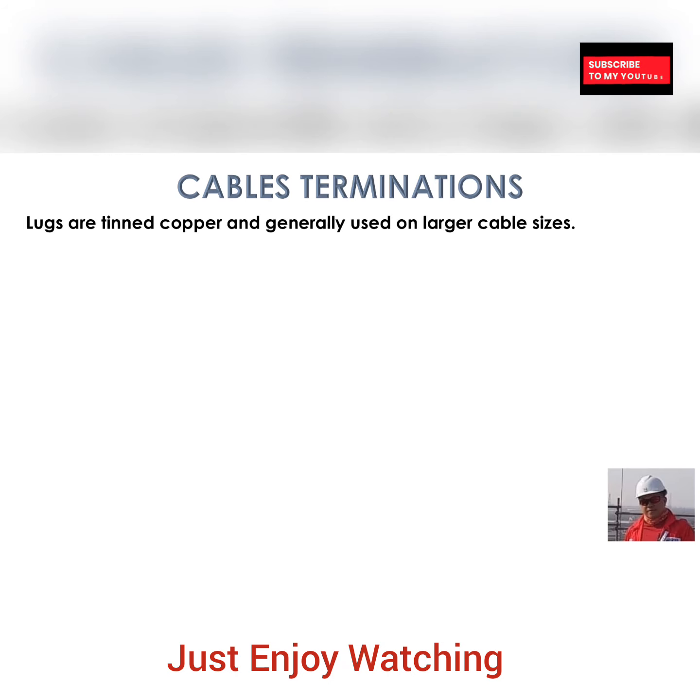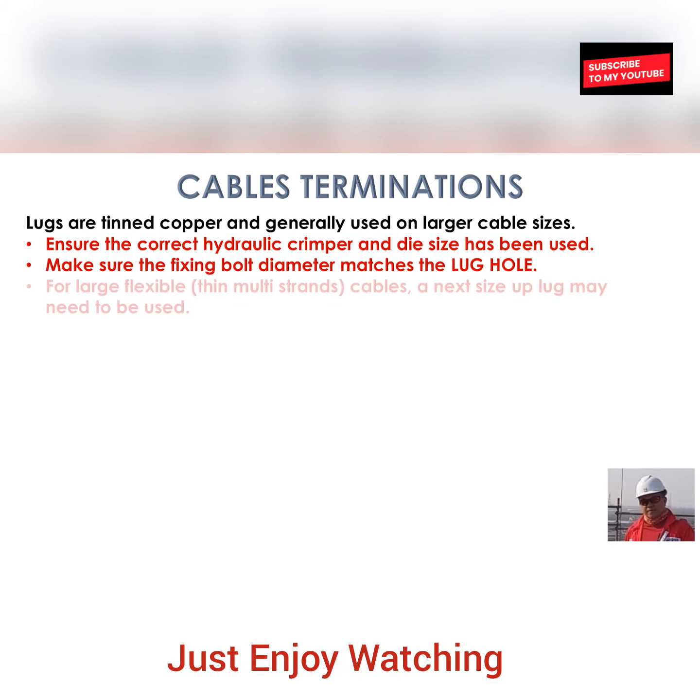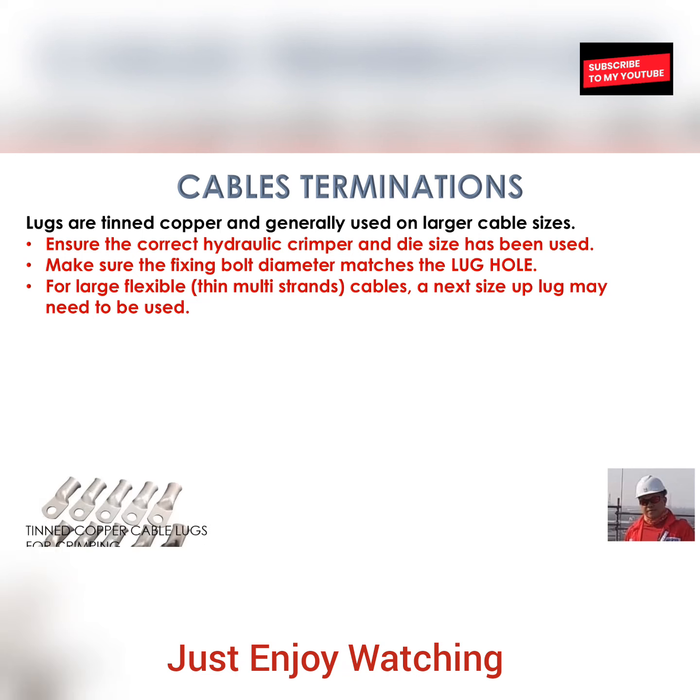So lugs are thin copper and generally used on larger cable sizes. So ensure the correct hydraulic crimper and die size has been used. Make sure the fixing bolt diameter matches the lug hole. For the large flexible cables, a next size of lug may need to be used. That's why you need to know all of this.